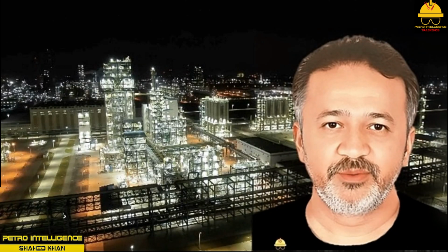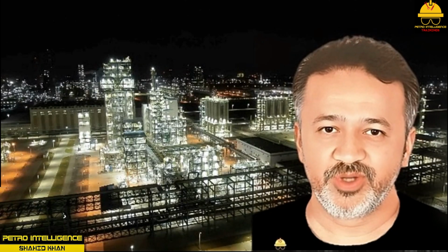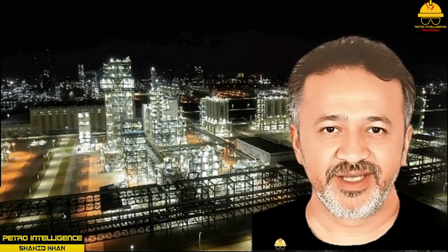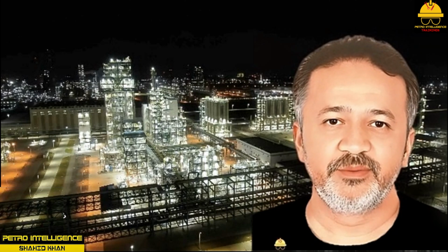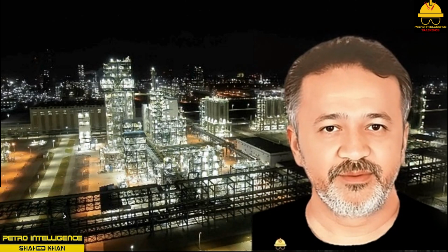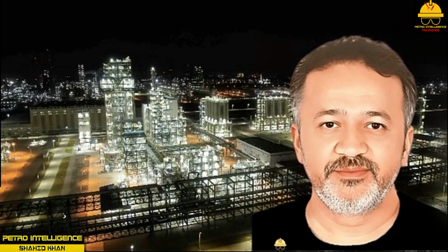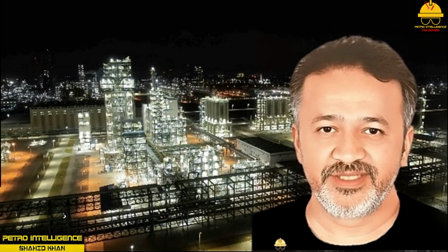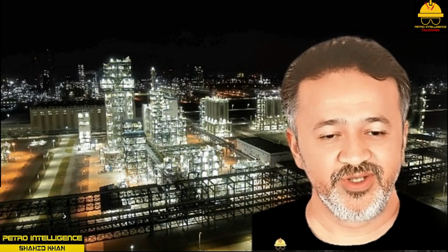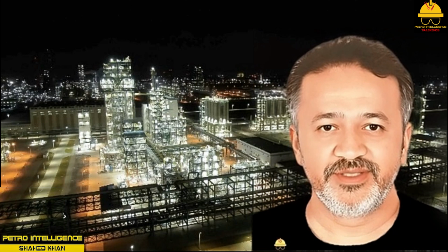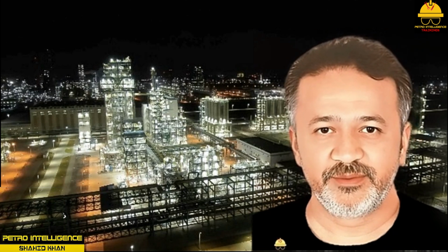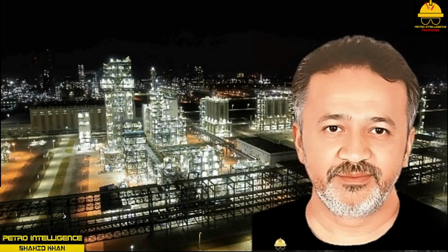Pressure control loop. A pressure control loop design uses the 5 elements of the control loop. The area to be controlled is a special vapor disengaging cavity that allows vapors or gases that are compressible to be controlled at a set point. The one area that changes consistently is the first primary elements and sensors. Pressure-controlled loops use devices to detect pressure changes. These primary elements are typically expansion-type devices.